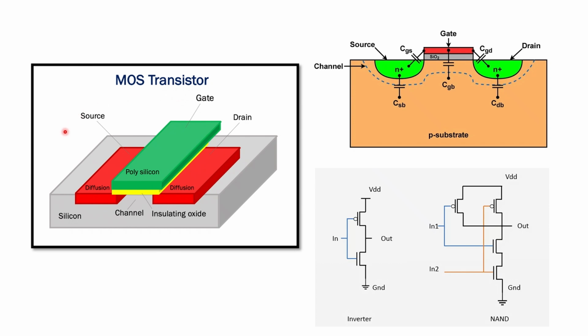switching devices. But beyond that, people found out the ability to put many of the MOS transistors on the same substrate. This is called coplanar integration. So on the same substrate, you can interconnect the gate metal and the source and drain, and you can form different kinds of inverters, different logics, different memory devices, and so on. So this is a very versatile building block.